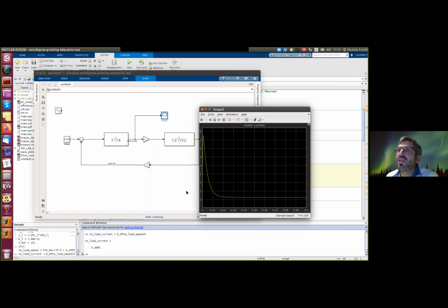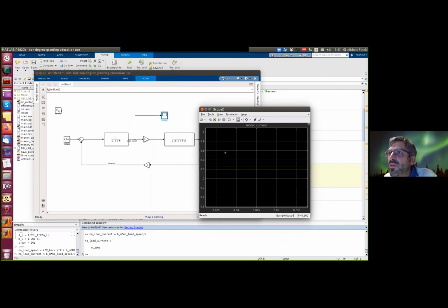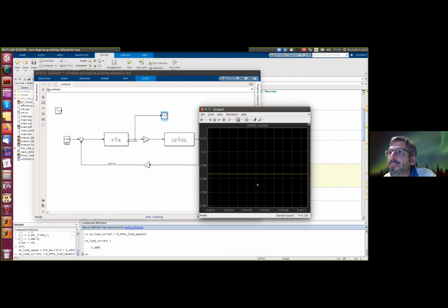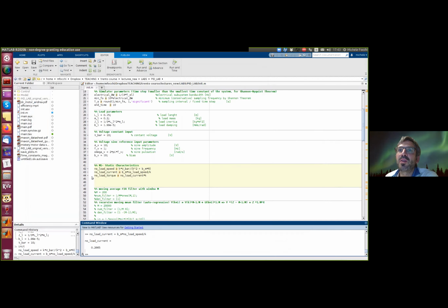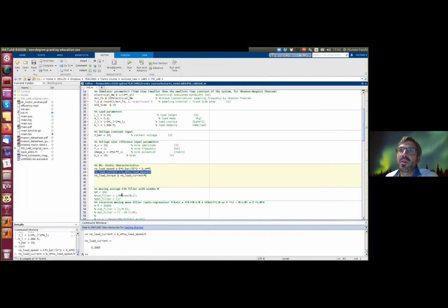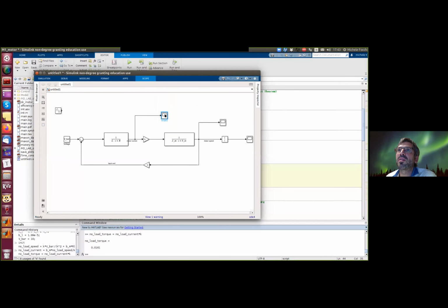If you open the scope, motor current, now it's something like that. And the no-load current after the initial peak, you see that it is around steady state value, and it's supposed to be 0.26, and it is exactly matching with what we found by our equations. And the same for the no-load torque, which will be 0.01, that is just multiplying the no-load current times the torque constant. So we miss one plot for the motor torque, that is here.